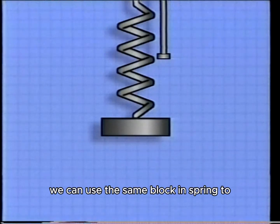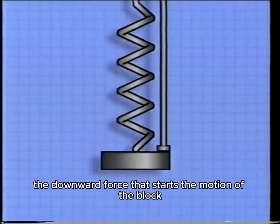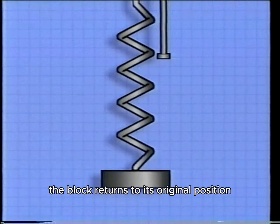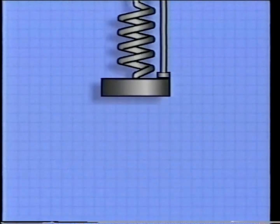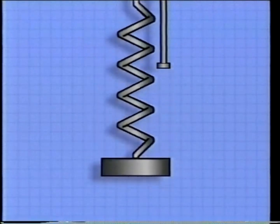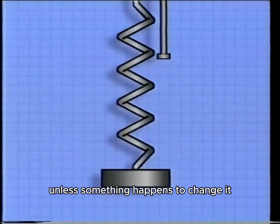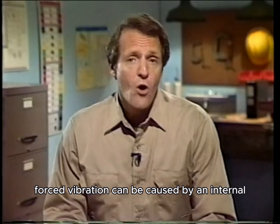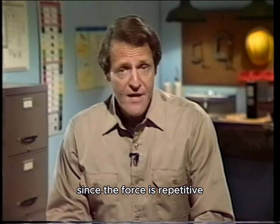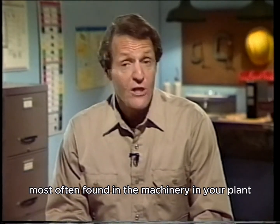We can use the same block and spring to illustrate forced vibration. In this situation, the downward force that starts the motion of the block is repeated each time the block returns to its original position. As a result, the block travels about the same distance each time, and it will continue to travel the same distance unless something happens to change it. Forced vibration can be caused by an internal or an external force. Since the force is repetitive, it resembles the type of vibration most often found in the machinery in your plant.